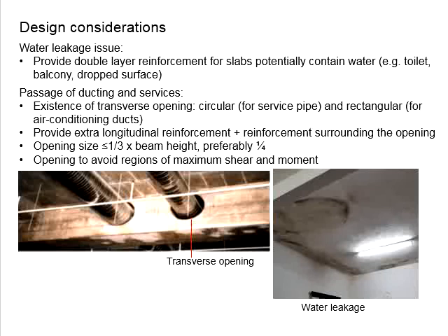On this note, you will need to provide a typical design to strengthen the circular opening as well as the rectangular or square openings. Clearly indicate how the reinforcement bars are arranged, as well as the size and number of the reinforcement bars. You will need to provide adequate anchorage length so that the reinforcement bars can act effectively in controlling the cracks.